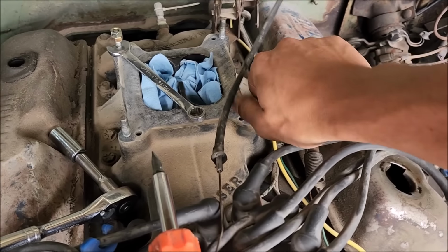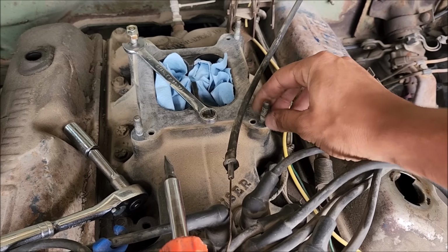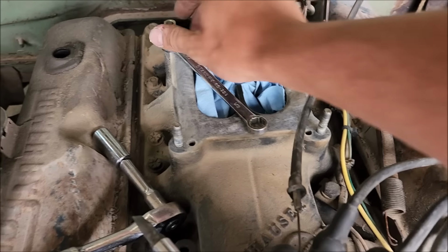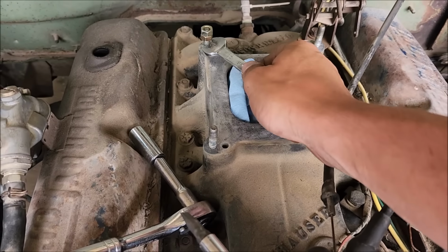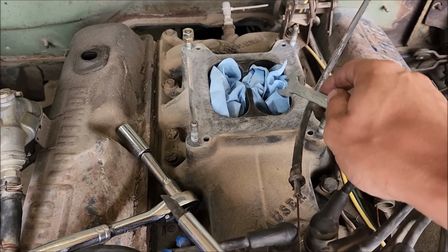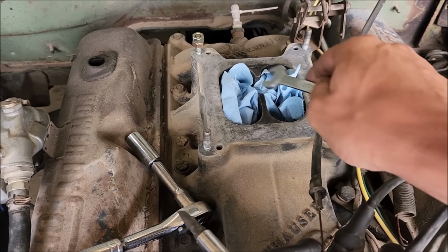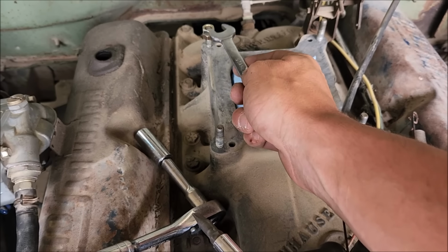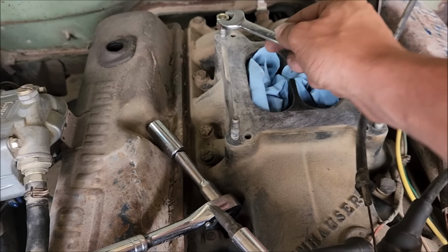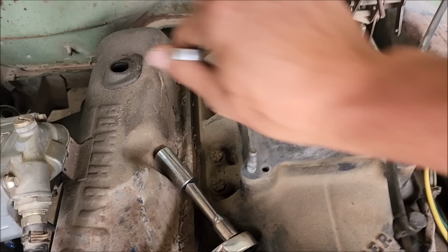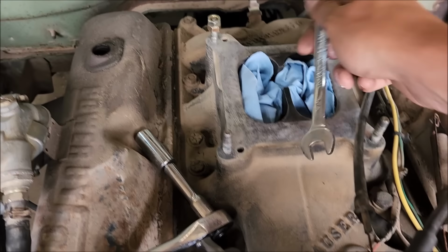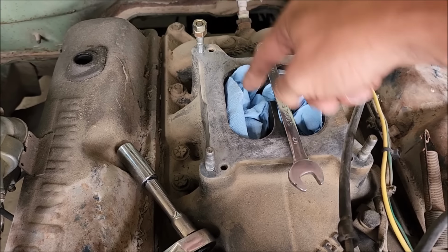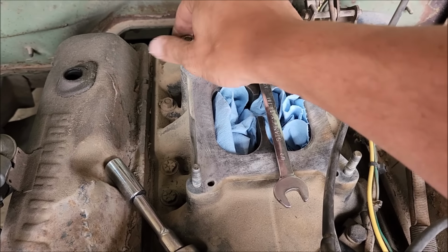All right, so installing the Carb Cheater spacer here, you need to change out your studs. Now, sometimes your studs will be loose, sometimes they'll be real tight. So you definitely want to put some rags in the intake. The last thing you want to do when you're trying to do this is drop anything in there, and then you're going to have a really bad day. So anyway, I just jam nutted 2 of the stud nuts together from the original stock here, and then easily broke that loose, and then out she goes. But again, please don't drop anything in your intake when you're doing this. Be patient.